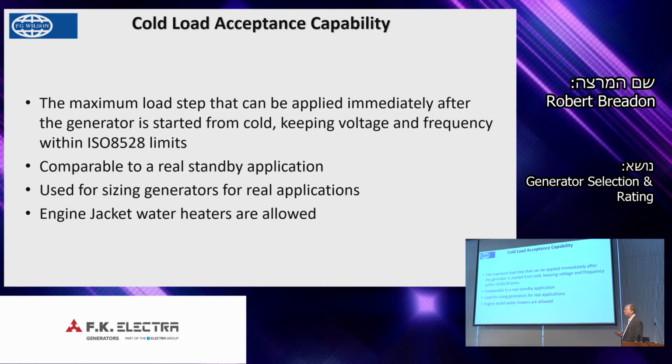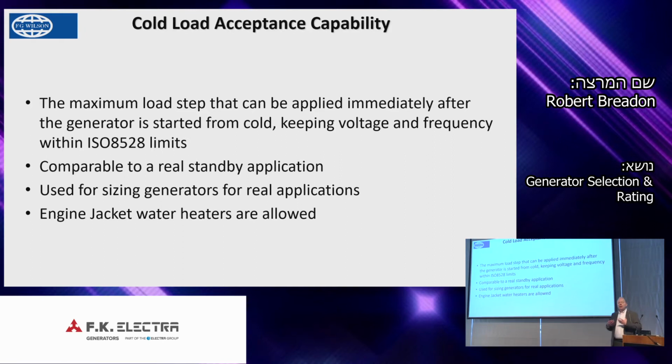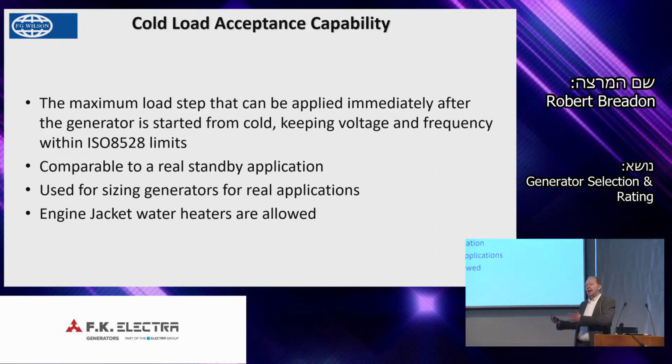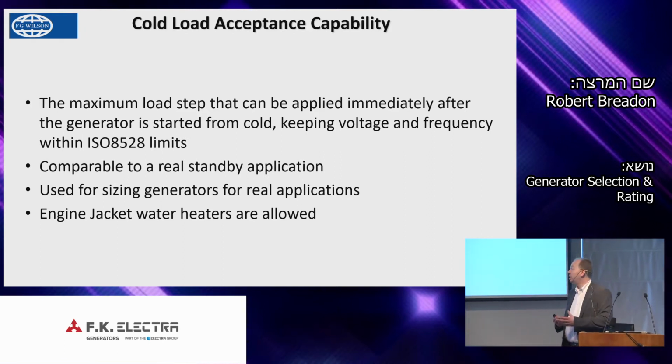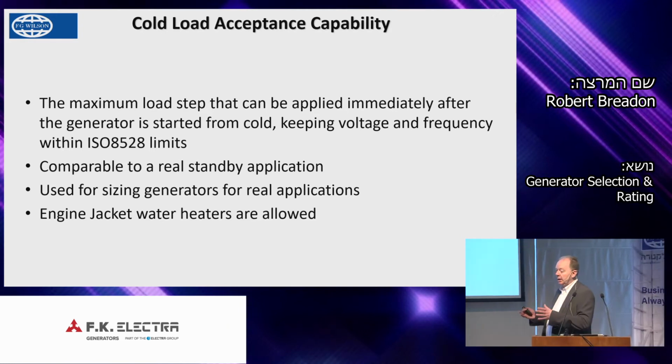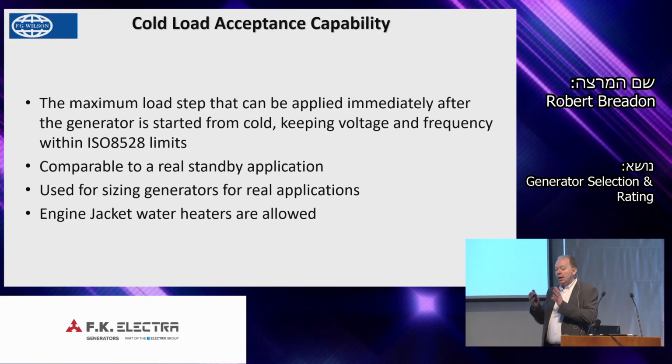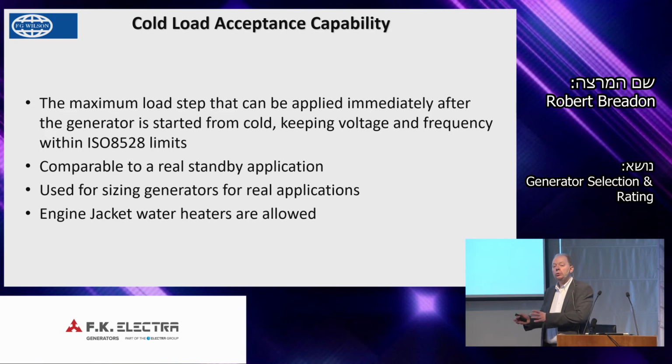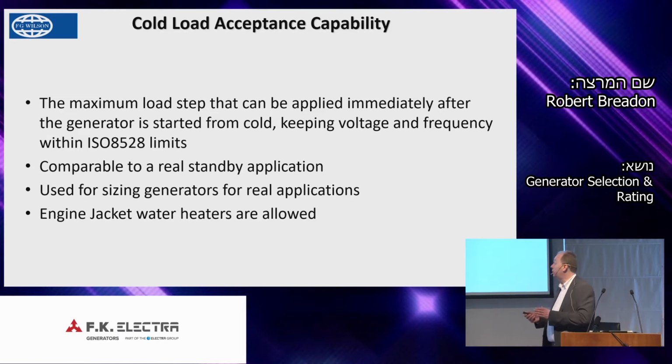Probably one of the most important tests that we do is cold load acceptance. A cold load acceptance is really a real-world incident for a standby machine. If a machine is sitting in a critical environment and it has to start and provide the load, we want to know how much load that machine can accept in its first load step.